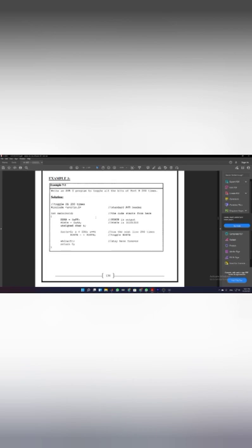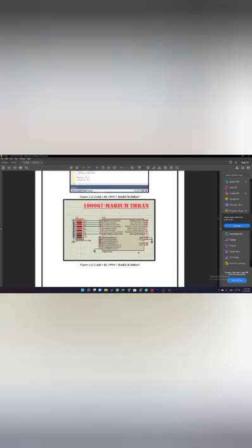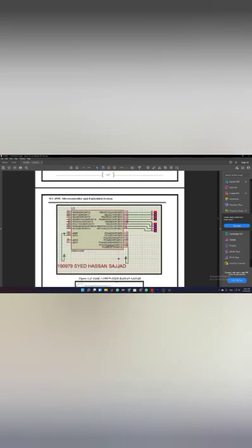So here we will declare port B as an output, and now we are giving a particular value to port B. Then an unsigned character Z is declared, and from Z equals 0 to 200 port B is toggling, meaning the execution of this for loop will happen again and port B will be toggled.